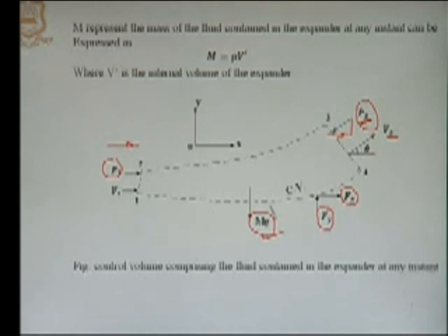Now, weight is acting in y direction. So, it will have no effect in x direction because the angle is 90 degrees. Fy also will have no effect in x direction, and in x direction we have force Fx, right. So, this is the force in x direction due to the body force and surface force. Since flow is a steady flow, we do not have to consider the acceleration effects or force due to acceleration, right.